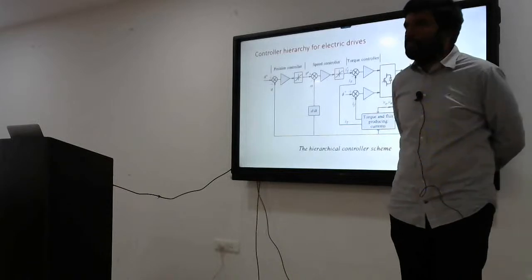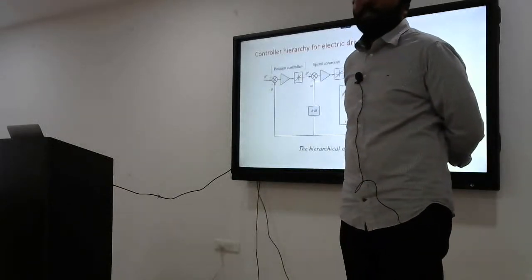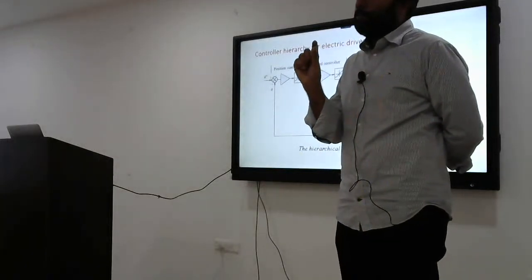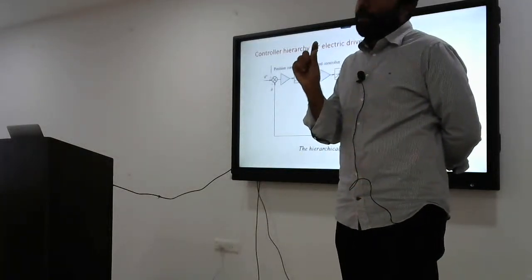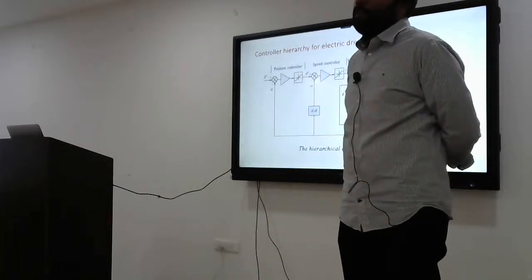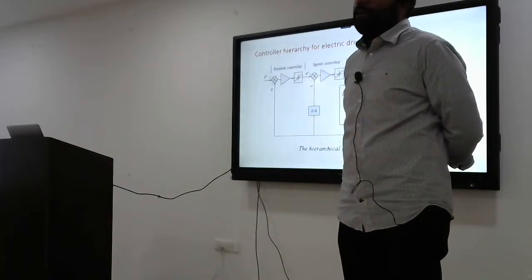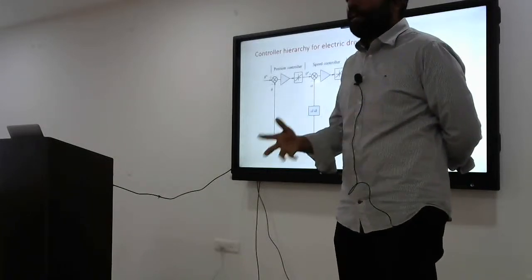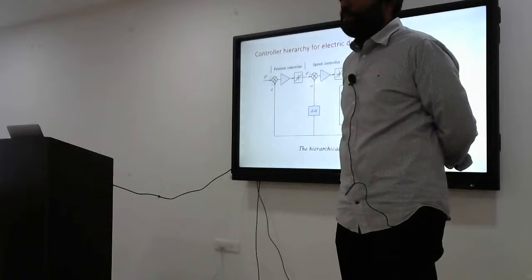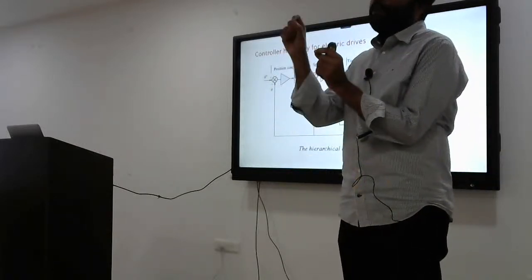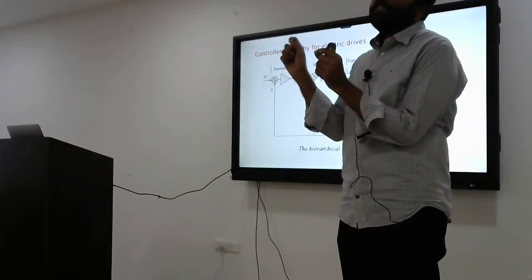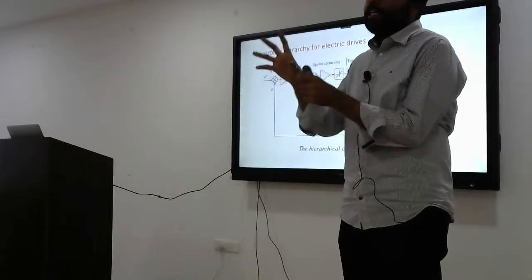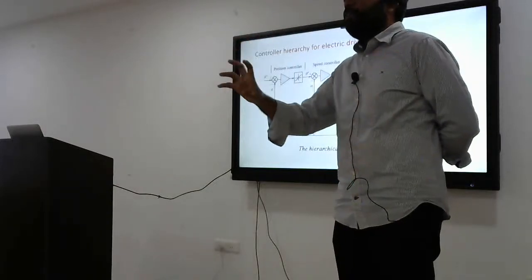You have studied control system subject. Third year students, you have studied control system. You heard about PI controller, PID controller or P controller or I controller, integral controller. See, if you take any controller, P controller or I controller or PID controller, input to the controller is always error. Am I correct or not? Input is error. What is the output of the controller? It is a cause component. Output of any controller will decide the magnitude of the main cause component.